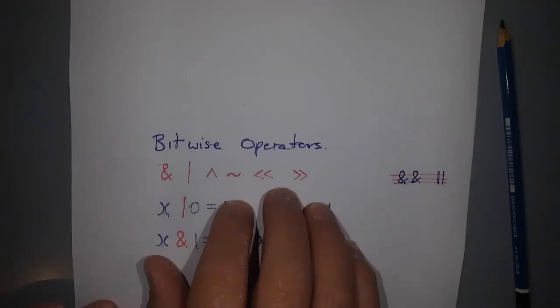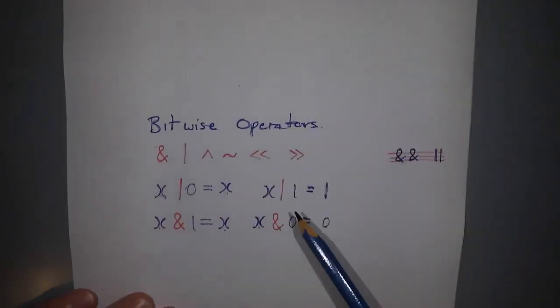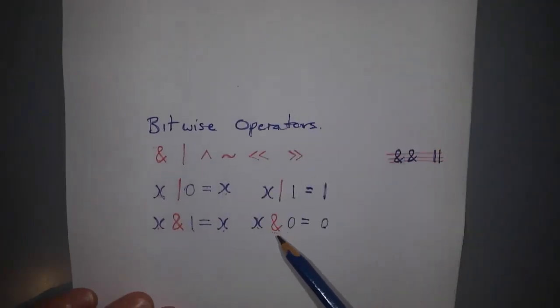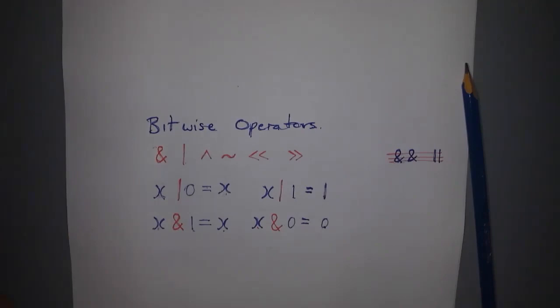If I look at my Boolean identities, if I AND something with 0, I force it to 0. If I AND it with a 1, I keep it the same. So that means here that port B is getting forced to 0. Those 3 are getting forced to 0. What's the effect of that in our program? Let's step through our program.